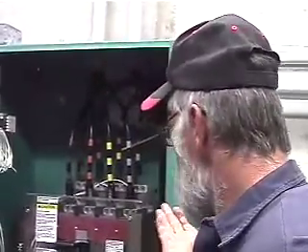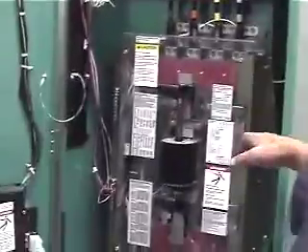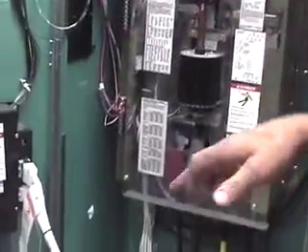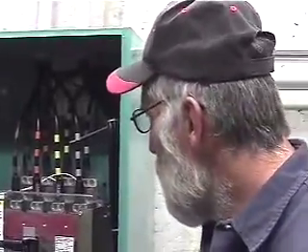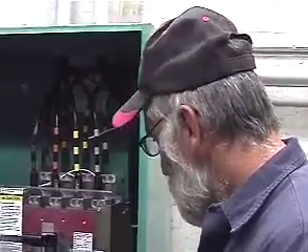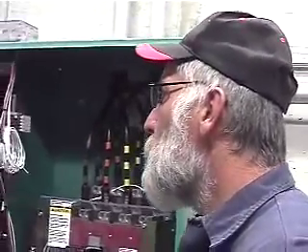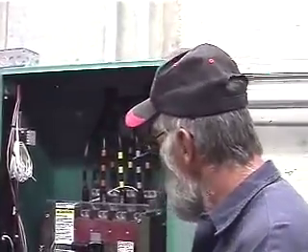Basic parts of a transfer switch. If you ever have to manually transfer this, you need to turn off the generator, turn off utility power, grab the upper handle, move it to the center, grab the lower handle, move it to the center. Never use both handles at the same time because the bar will never end up being where it's supposed to be. So, this particular transfer switch is a 300 amp transfer switch.